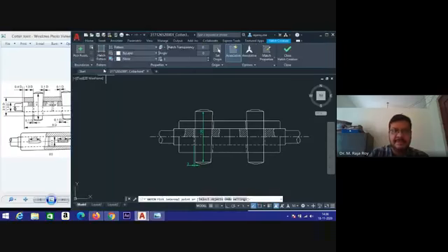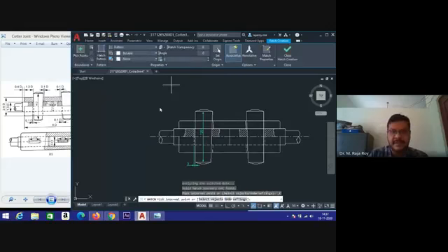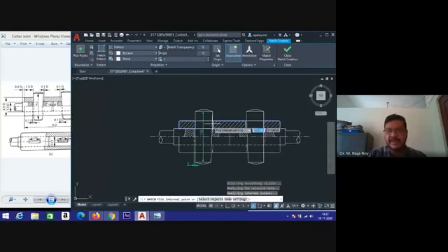Again go to the hatch command. So here the hatching scale you can increase. See? Hatching scale, this you can double now. And you can increase and select this point. These 3 points you can select. Okay.